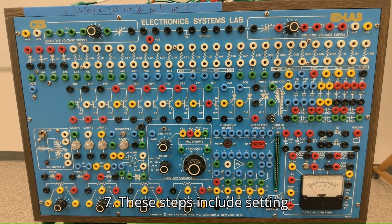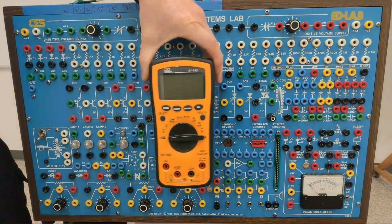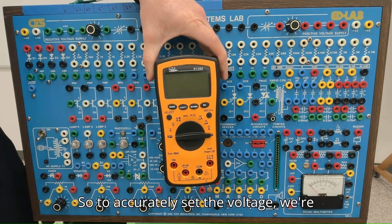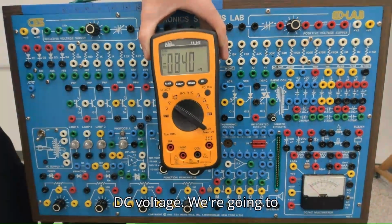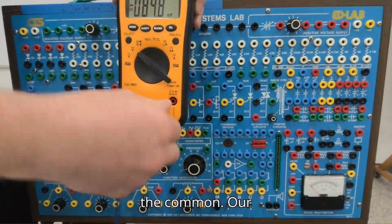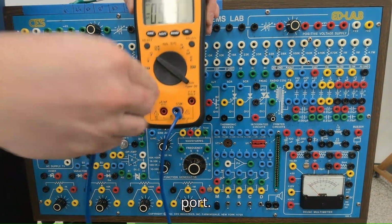These steps include setting voltage, identifying resistors to be used, resistor measurements, installing the jumpers, and measuring resistance, current, and voltage within the circuit. The first step is to set voltage. To accurately set the voltage, we're going to use our multimeter here. We're going to have our multimeter in DC voltage. We're going to install our leads, one into the common. Our second lead will go into the voltage port.